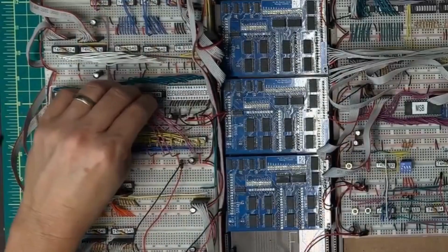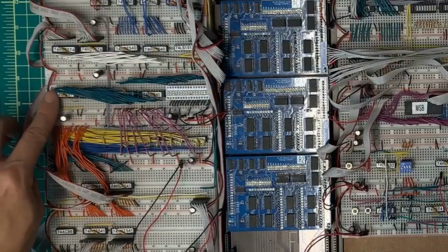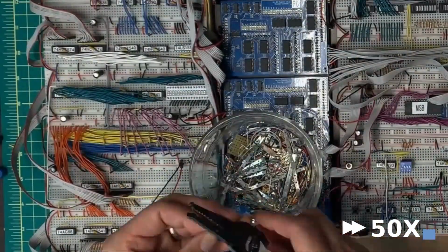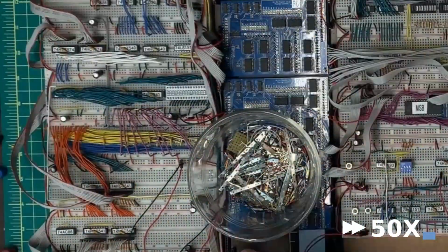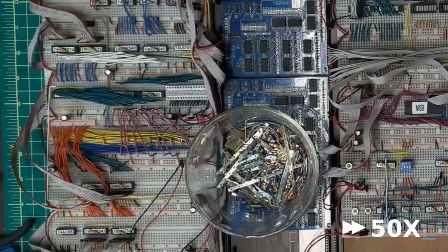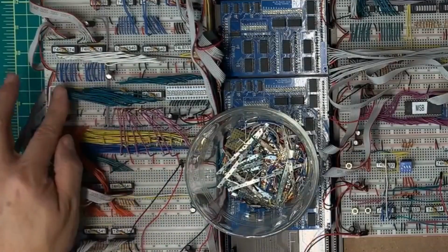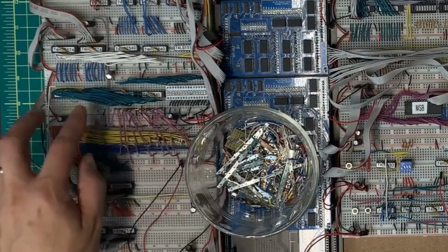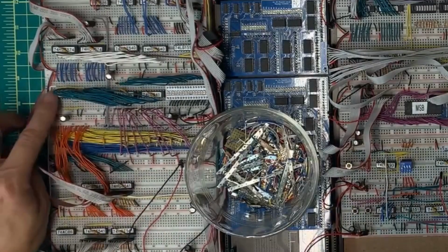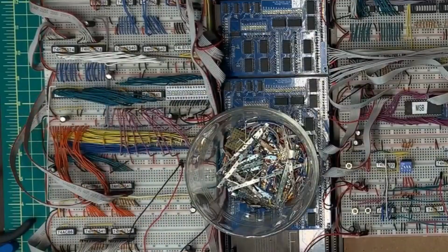Okay, two fundamental changes left. I need to tie the outputs of the line drivers up to the inputs to the latch. That basically establishes my ALU bus. The next thing to do is take all the adder outputs and wire those up into the line driver for, you know what? I've made a mistake. I've got LS logic still in here. I need to swap those out for HCT. Let me do that before I go any farther.